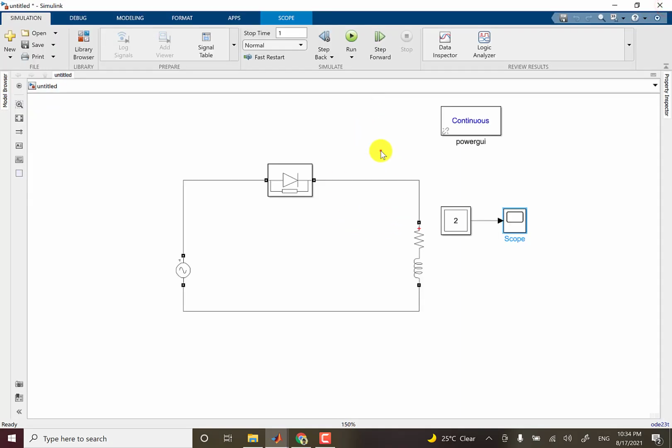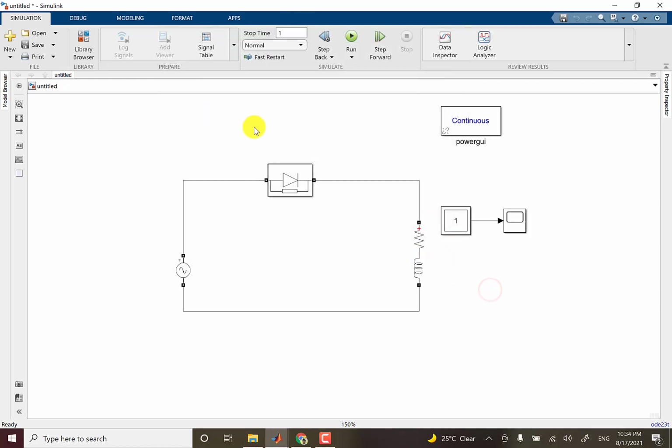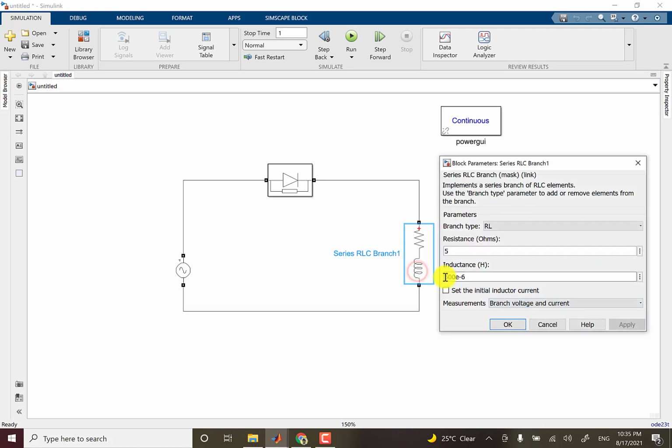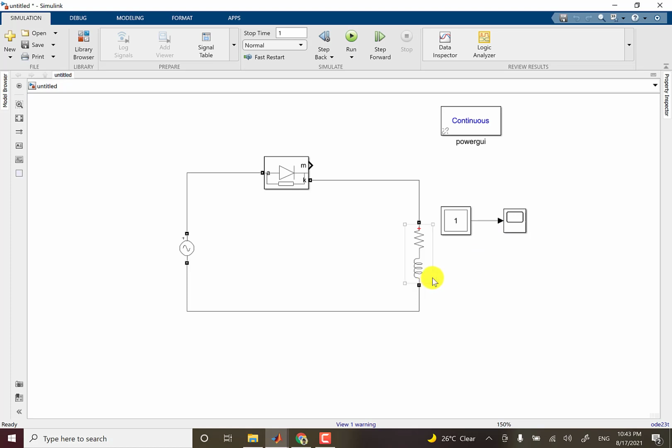Okay, so one way to keep track of it, I'll remove this load current and just observe the voltage for different values of inductor. One good strategy to demonstrate the effect of this inductance on the output voltage is to use different values of inductor and see the output voltage.